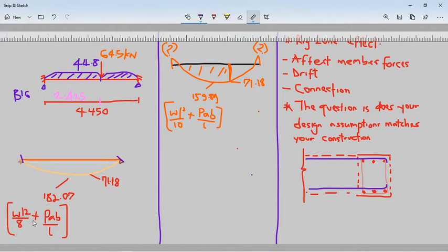And this is the formula that I use to come about this maximum moment here. And remember, there's an adjoining beam that serves as point load, so I have assumed that point load as well in my manual calculation, and this is what I come with. Again, I know that the software has fixed end moments in its calculation, because the analysis treats the structure as a whole, so everything is connected.